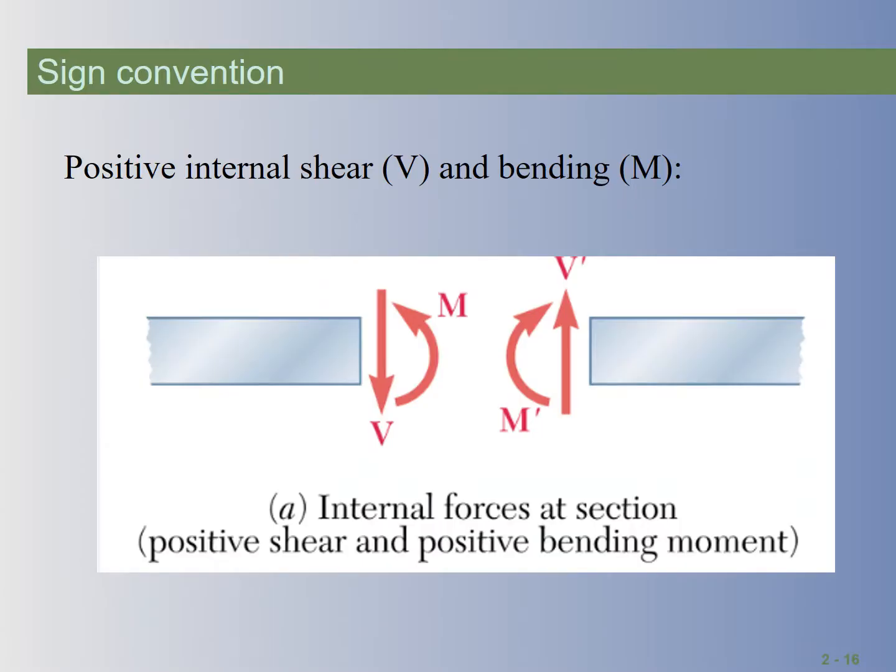And this, again, is that sign convention. So positive moment is unscrewing out of the board. So positive is counterclockwise, and they've just paired that positive moment and negative shear with both. We'll just call this pair positive. So both of them are positive.